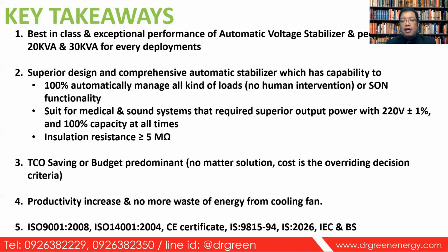Next, if you are looking for a stabilizer that is suitable for medical or sound systems, or some application that is very sensitive to voltage fluctuation, you can choose a stabilizer that delivers an output voltage of 220 volts plus minus 1%. 220 volts plus minus 1% is very important. And again, the capacity should not drop. This is a very key factor that we have discussed in today's topic.